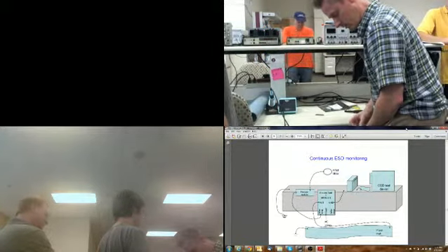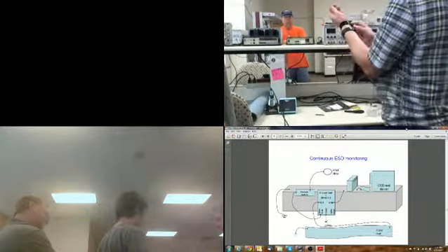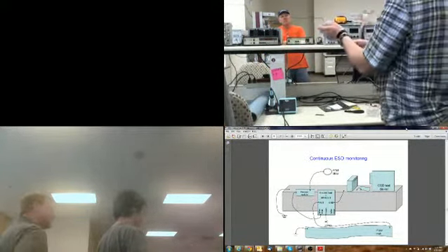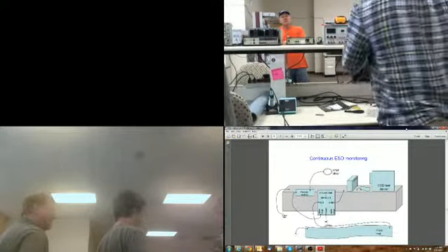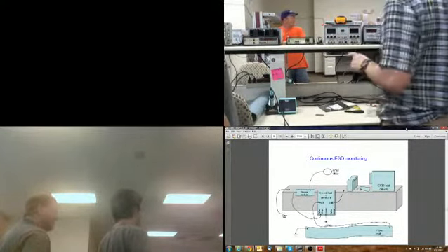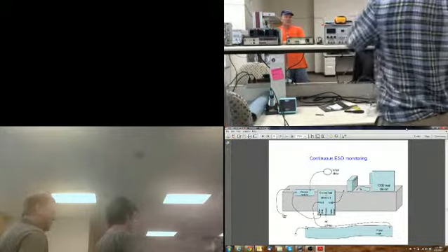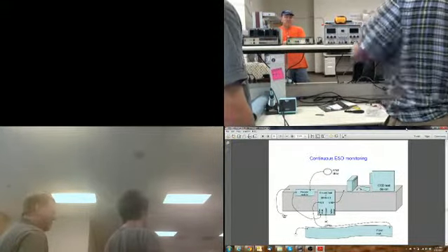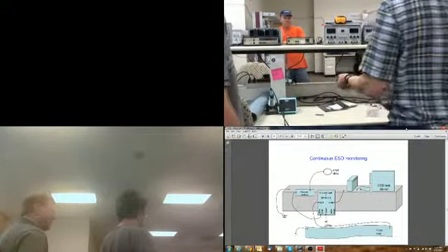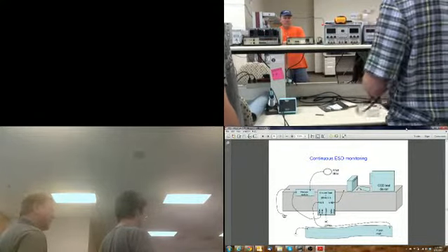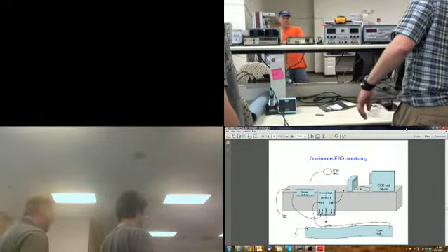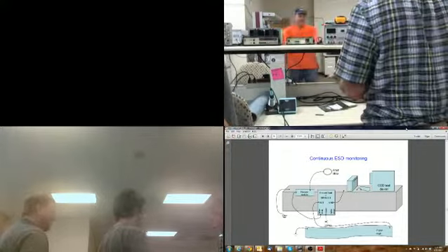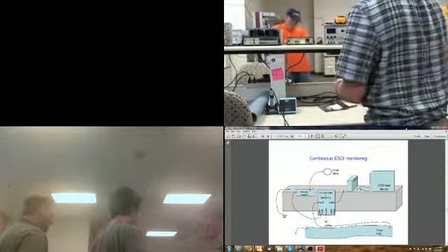Can someone help me? Okay. Actually, you can leave this on once you get it on. And then you would test it with a monitor system. You touch a panel on the wall and make sure that you connect to the ground. And then you connect this to your ground system. Then you pick up the part.